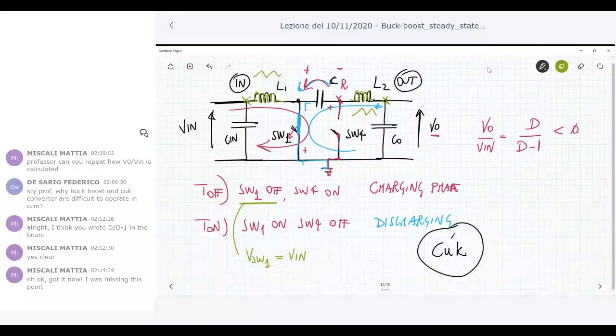There is a strict relationship between the R-on resistance of the closed MOSFET and the breakdown voltage. MOSFETs with larger breakdown voltages always have larger R-on resistance, which induces higher conduction losses, etc. So this can be a benefit.